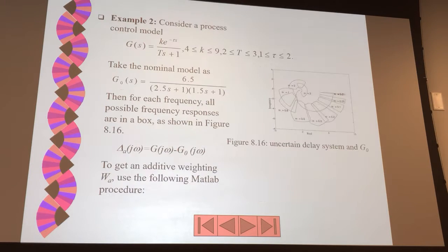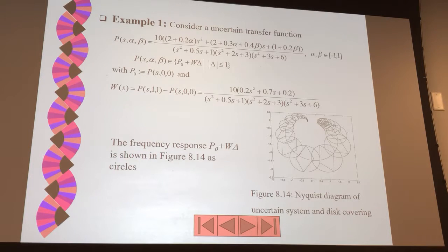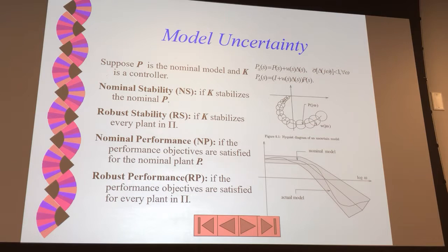So all these things can be obtained via scanning, via the code. This part is based on a SISO transfer function, but in the MIMO case, it's probably not that simple. But the basic idea is similar. You need to divide them. But specifically, given a problem, how to divide them in the optimal way with the smallest conservatism, that's still a topic of research. But we do have a certain systematic way to handle this divide and conquer problem.